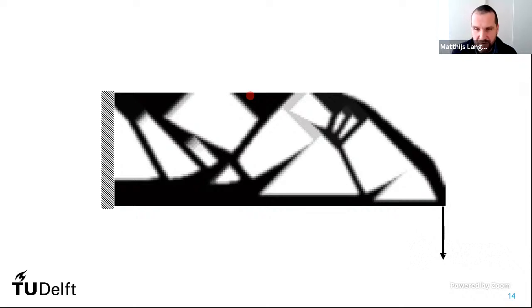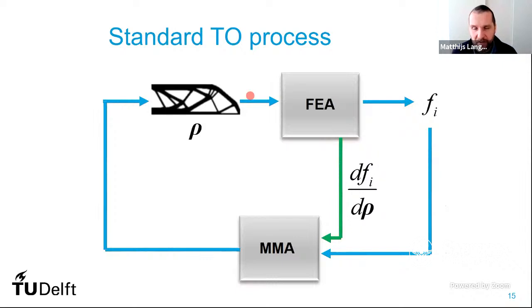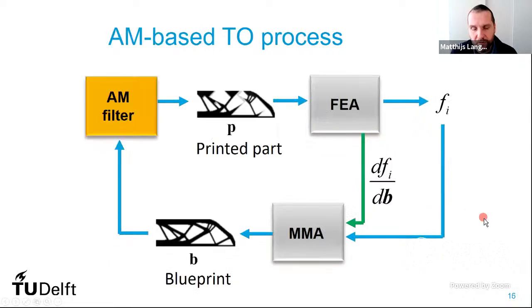So now the idea is, now that we have this geometric, you could say process simulation, very much simplified process simulation, but it identifies which parts is the printable part of a certain geometry. What we're going to do is, this is our standard topology optimization loop as I introduced it. I'm just going to place an operation in between here, that the suggestion that is obtained from the optimizer as a next design, I call that now the blueprint design. And that goes through this, let's say, additive manufacturing filter, which filters out the parts that can actually be printed. So this is the simplified printing simulation.